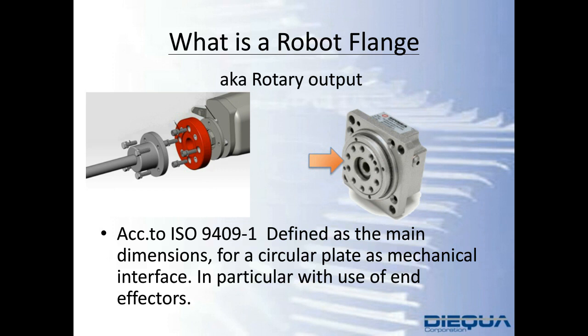And in most cases, you don't need the full 2,000 or 3,000 RPM from the motor at the load, where a reducer could give you the added benefit of not only torque multiplication, but also gets you into the speed range that you're looking to accomplish this motion. Also, for people in the servo industries, you'll be familiar with inertial matching, right, where this allows you to handle more dynamic handling of rather large loads without concern of overloading the motor.